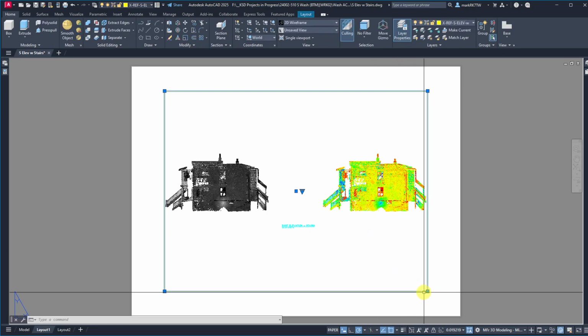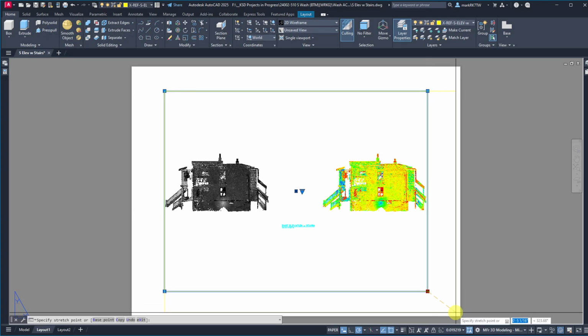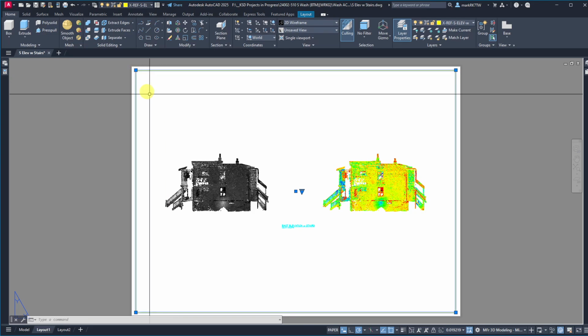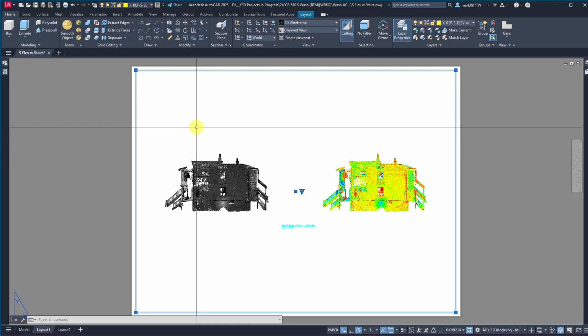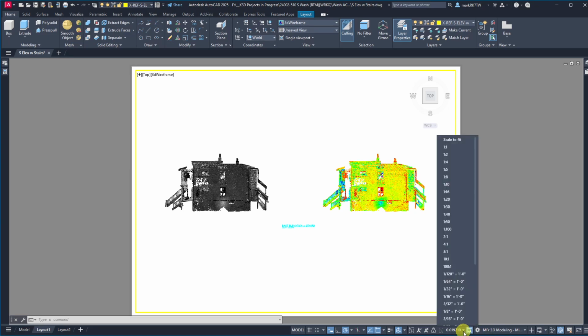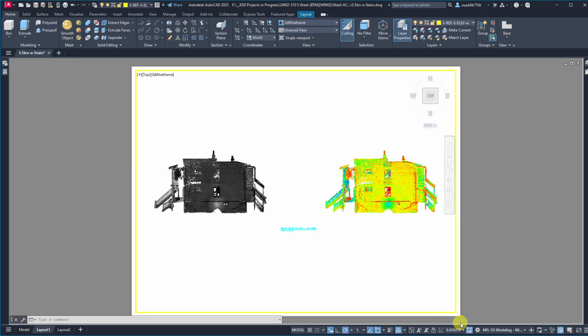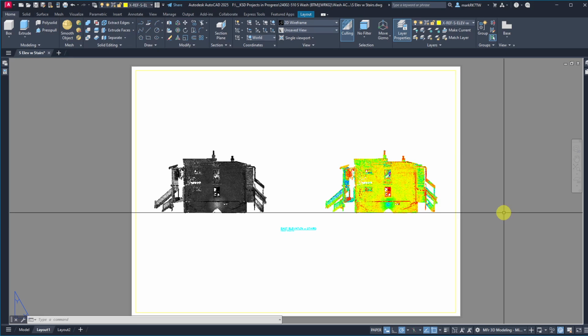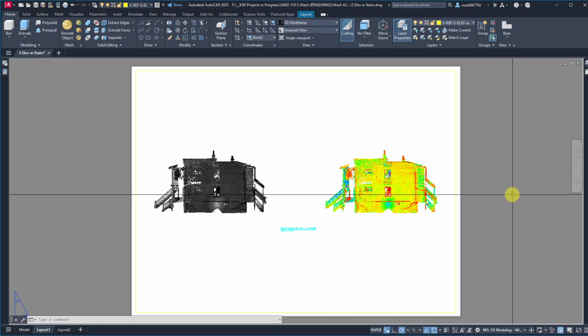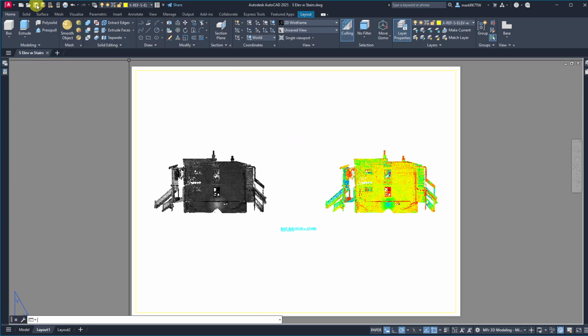Now my viewport, I just know from having done these on the other elevations that I'm going to need it larger. So I'm going to change my viewport, make it larger, and now that it's larger, I can double click inside of it and then make my scale 1/4 inch, and you'll see that it worked out very nicely in this case. You have to find your own scale, how you want to do it, and how you want to bring it in to your master drawing where you're saving all of your stuff. So now that I've got that set, let's go ahead and save it.